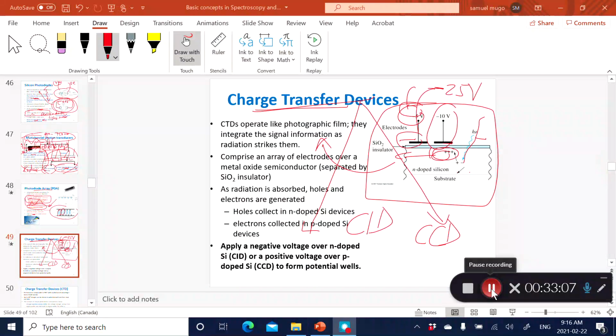So the charge coupled device is where you keep moving these holes to a charge amplifier. But as I said, you can operate it as a CID, where you're just simply measuring the voltage, the potential difference, as you move these electrons from one electrode to another.